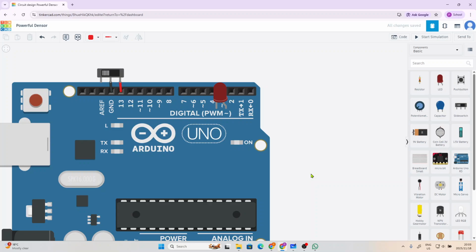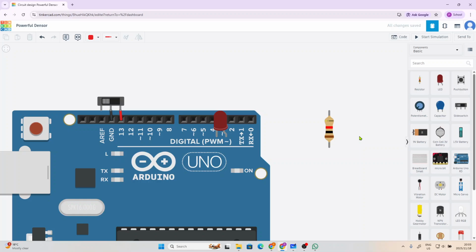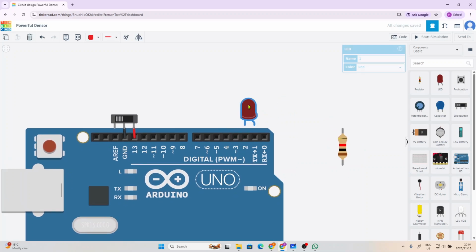Using simple calculations, can you tell me what ohms it should be? How many ohms for the optimal use of an LED in this case? You should know this. Oh, you're asking me? Yes. What ohms should I set this resistor to? 10 ohms, I guess. Boom, you blew your LED.